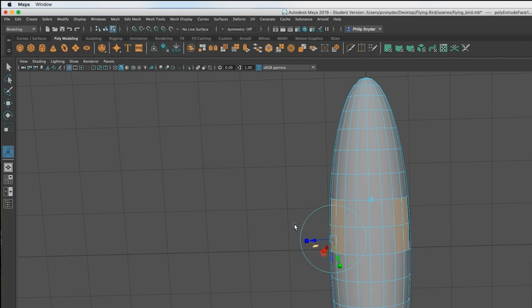Now you'll notice that these controls here, we have move tools and we have scale tools, but we don't want to use the tool this way. What we want to do is use the scale tool so that we scale these out and the extrusions go straight out. So press R, and now you'll see it centered up between them, so that it'll extrude straight out in both directions. So we'll go out 1 move, and then